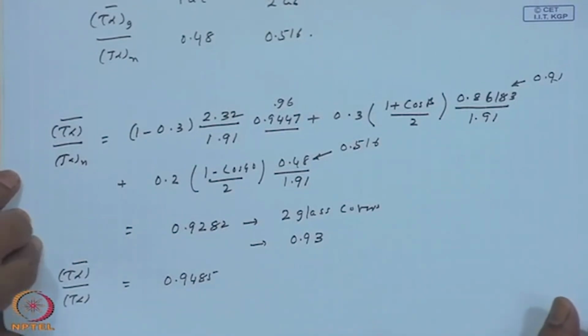So, as I was emphasizing, this 1 plus b 0 into 1 by cos theta minus 1, the incidence angle modifier coefficient relation for tau alpha by tau alpha n, in general, depending upon the theta that you use for the direct radiation or the diffuse radiation or the ground reflected radiation, will give you the appropriate tau alpha by tau alpha normal. So, we got this.